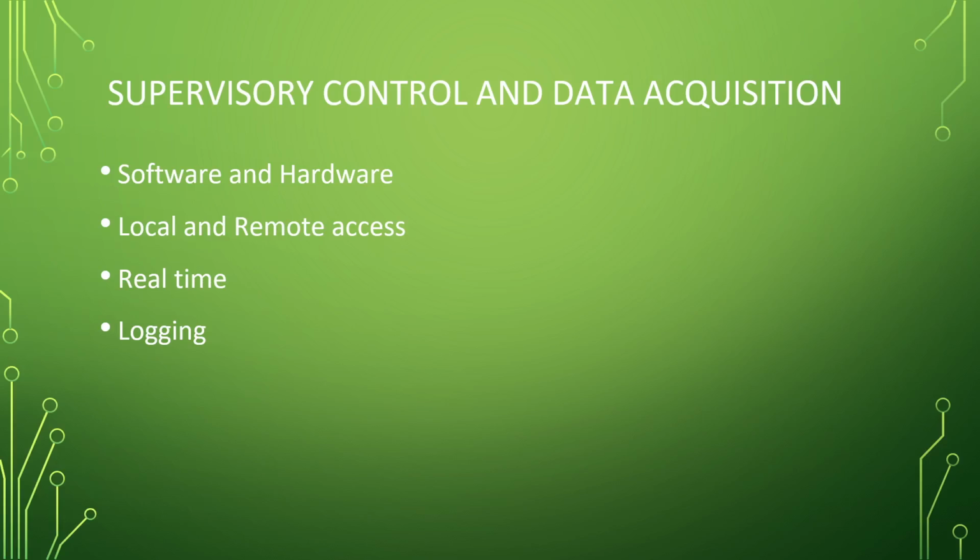I know at some of our local companies around here they have PLCs, but each station is its own little entity. It's not networked at all. If you want to use that station, there's an operator sitting there loading it and pressing buttons. The PLC is still running the whole show, extending the cylinder for this long and doing all these other things, but they're not talking back or sending data anywhere. So you can have self-contained little PLC networks, or massive ones that are all networked together, like our little robot station down there. There are 5 different Siemens PLCs on that, all networked and talking to each other.